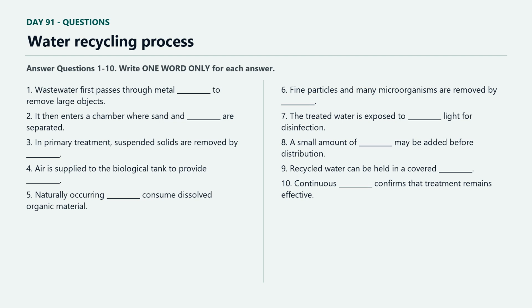Continuous instruments provide immediate information, while laboratory tests check microorganisms and chemicals that cannot be measured reliably every second. Records allow regulators and operators to examine trends rather than respond only to one isolated reading. Quality assurance also includes equipment maintenance, calibration, staff training, emergency plans, and independent review.